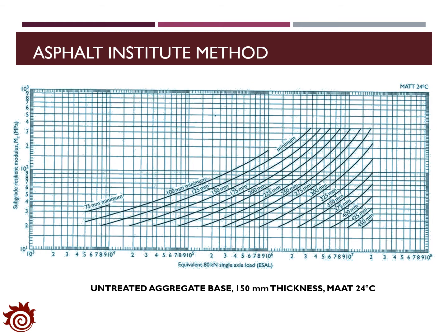Moreover, if the mean annual air temperature is higher than 24 degrees, where we don't need to think about the frost effect, then we can use the chart here for the estimation of the thickness of the asphalt layers for the deep strength asphalt pavement. And this chart is applied for the pavement which the granular base has the thickness of 150 millimeters.